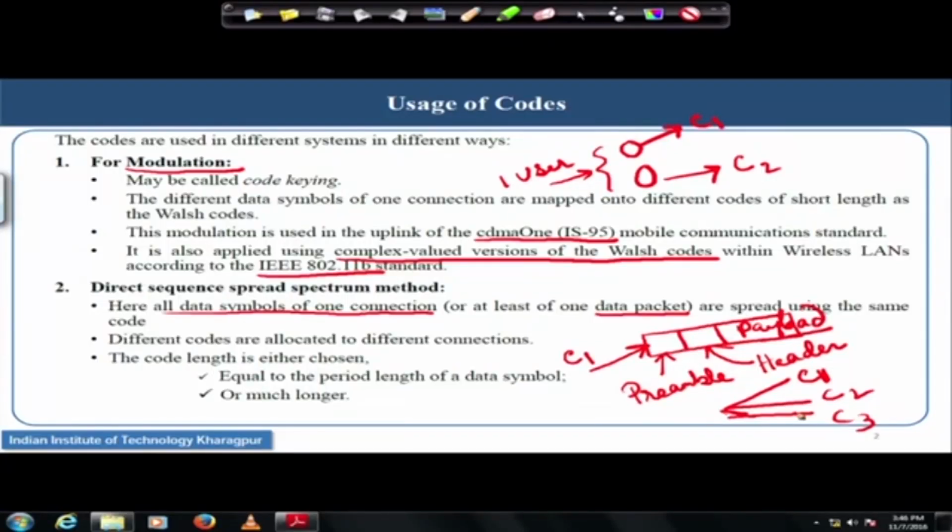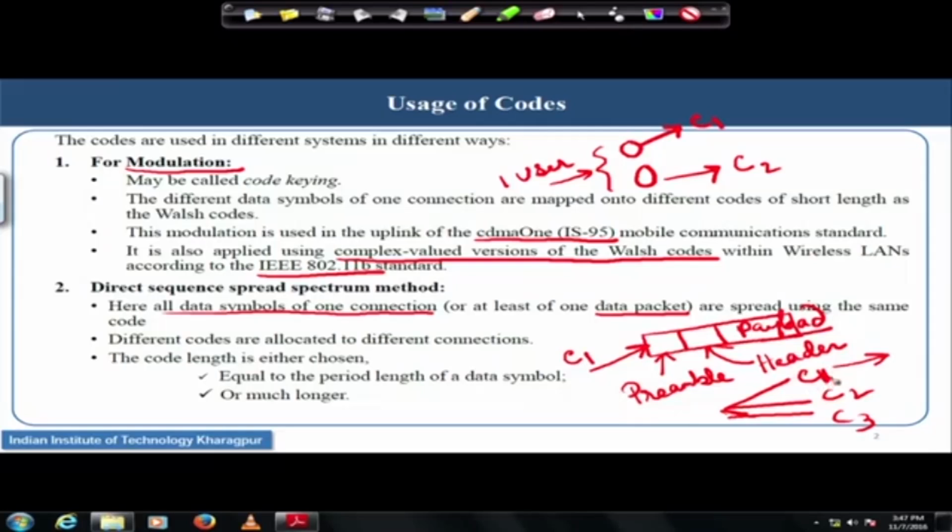How the signals from one user to the next will be differentiated is such that a receiver will always multiply the combined received signal by his own known code. As the codes are orthogonal to each other, the cross correlation with the other codes over the symbol duration will be perfectly 0, and you will end up with your own signal extracted. That is the despreading procedure that we have already learned.